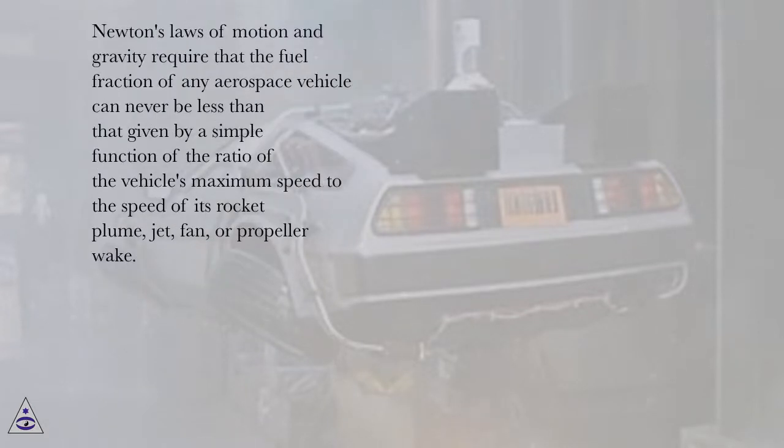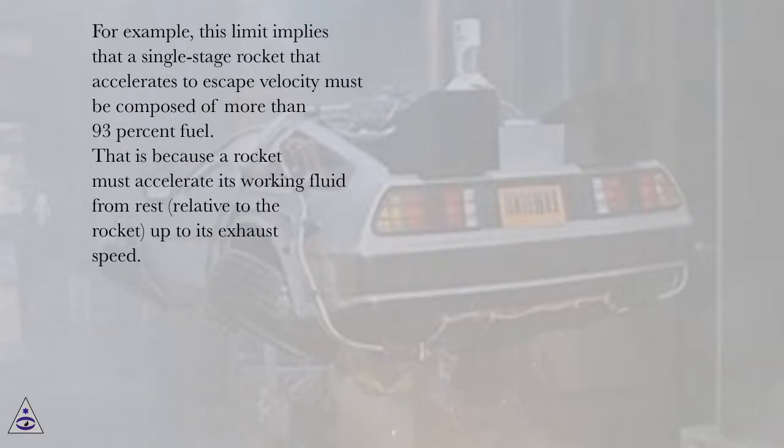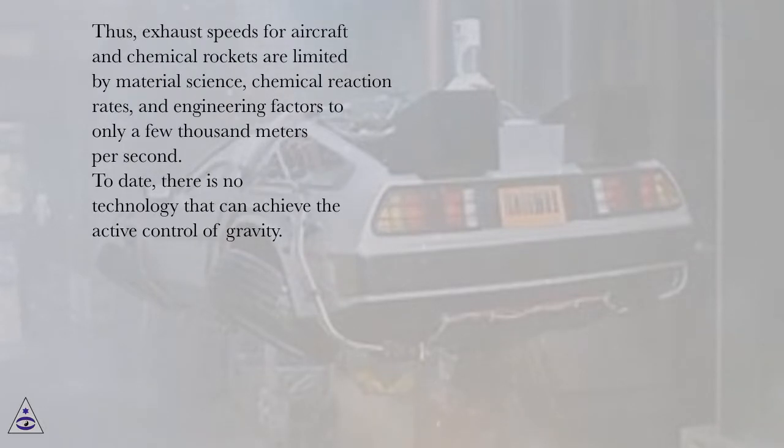Newton's laws of motion and gravity require that the fuel fraction of any aerospace vehicle can never be less than that given by a simple function of the ratio of the vehicle's maximum speed to the speed of its rocket plume, jet, fan, or propeller wake. For example, this limit implies that a single-stage rocket that accelerates to escape velocity must be composed of more than 93% fuel. That is because a rocket must accelerate its working fluid from rest, relative to the rocket, up to its exhaust speed. Thus, exhaust speeds for aircraft and chemical rockets are limited by material science, chemical reaction rates, and engineering factors to only a few thousand meters per second. To date, there is no technology that can achieve the active control of gravity.